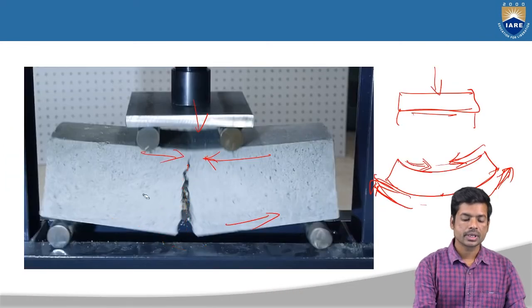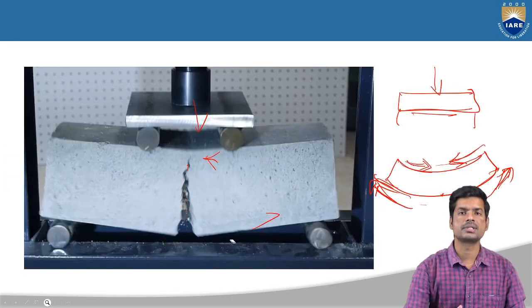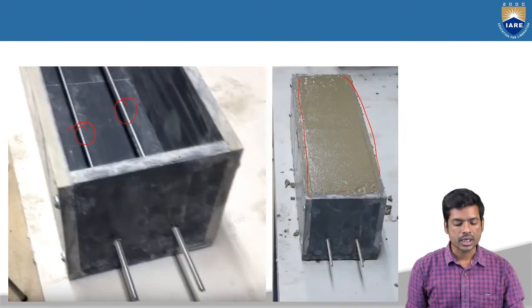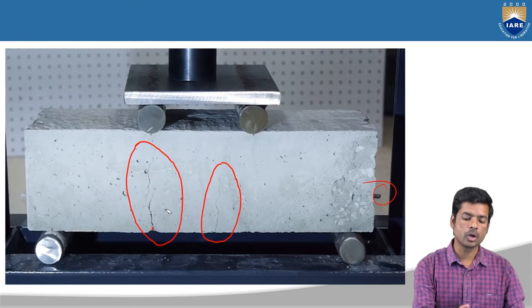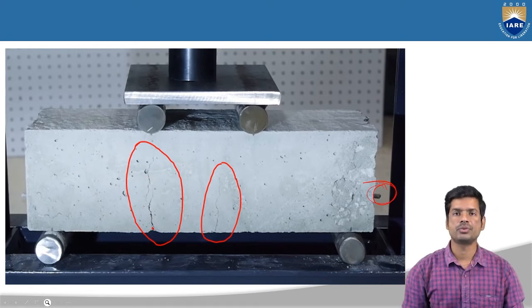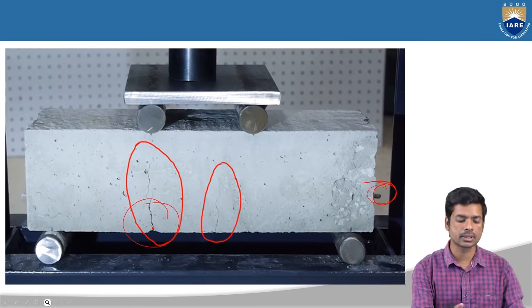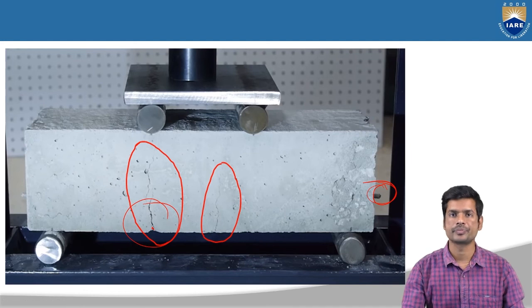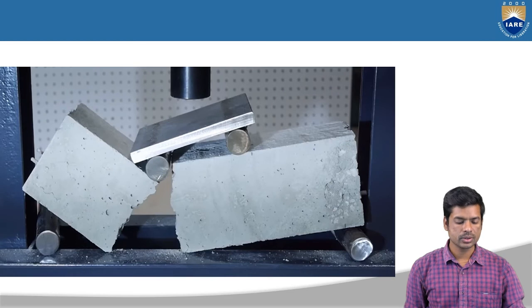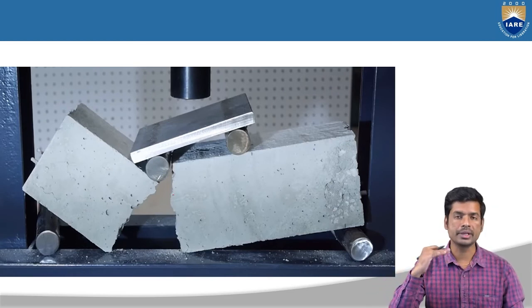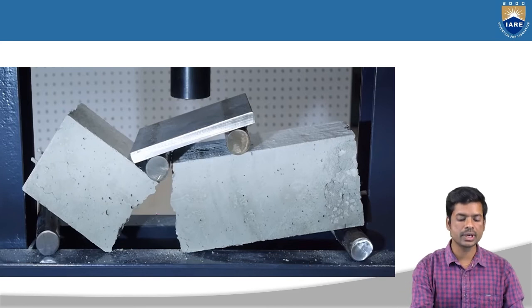So here the crack developed at one point itself, after application of the maximum load. But in the later picture, the crack is not developing continuously and suddenly. Because of this particular reinforcement bar, it is going to take tensile loads also. We may get the cracks, but that beam is not failing completely. That is the benefit of using reinforcement. After applying very high loads, it is going to fail like this.